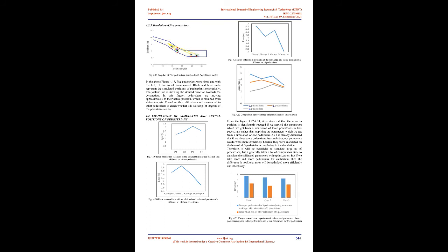As the density starts increasing, the average speed of the pedestrians starts decreasing, as it is difficult to maneuver in the high-density situation because of less space available, and also pedestrians generally maintain some distance from strangers. Therefore, if pedestrian density starts increasing, then the average speed of pedestrians will decrease, and there may be chances of a situation arising in which there is a full jam, meaning no movement at all.